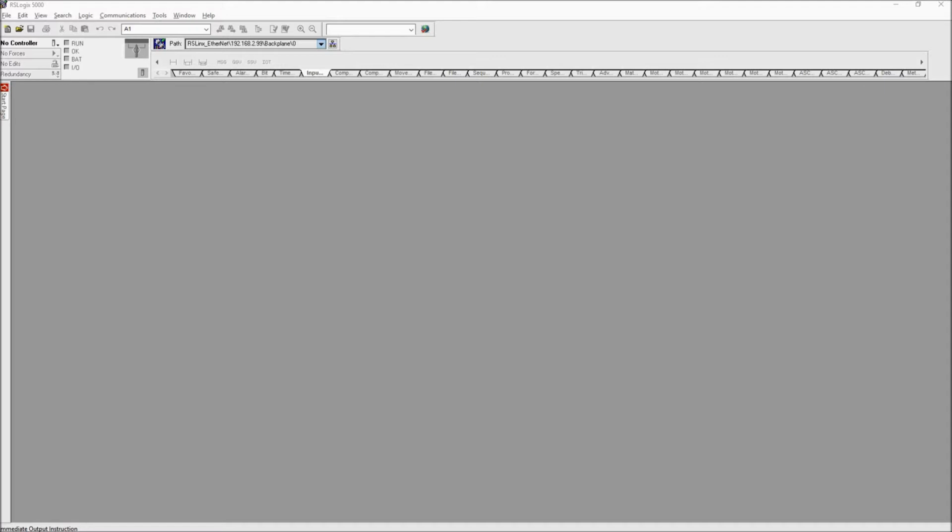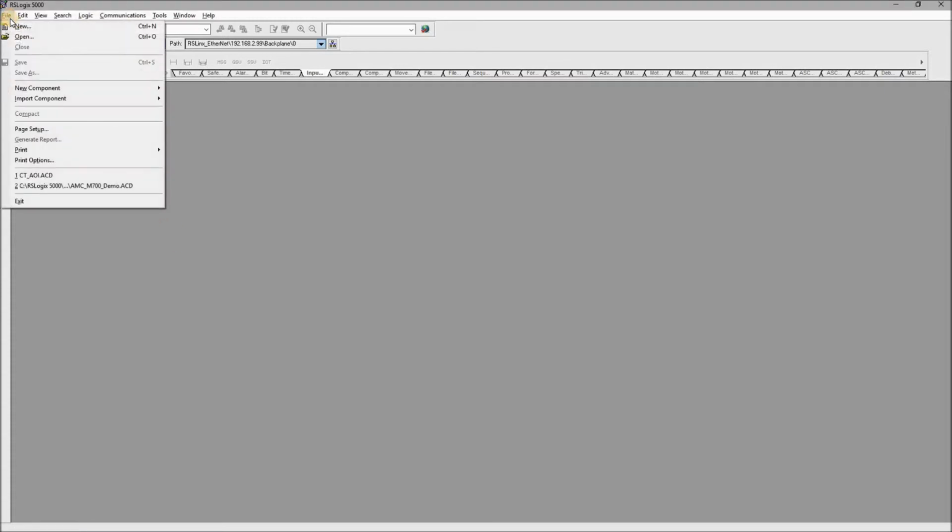As you can see here on the screen, I have RSLogix 5000 open. And for those who haven't seen the other videos, the PLC I'm using is a CompactLogix L32E. The first thing you need to do is come up to File, click New.